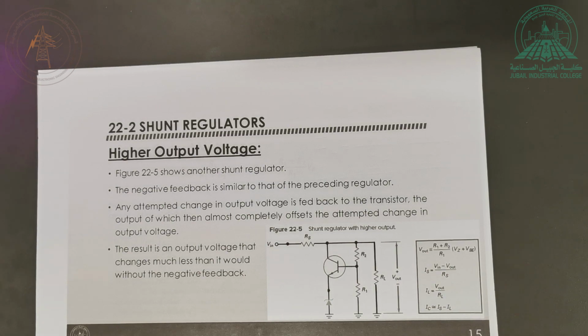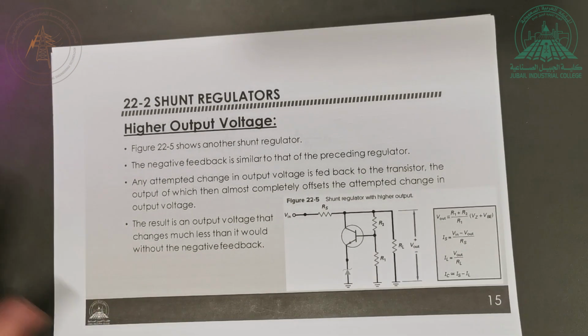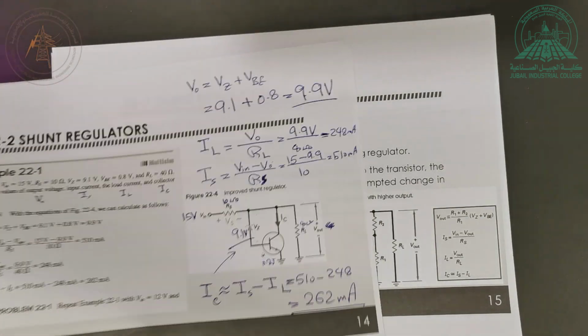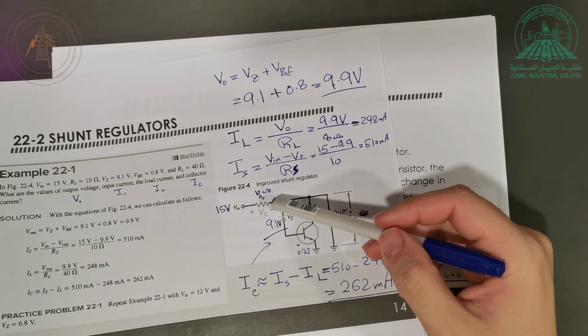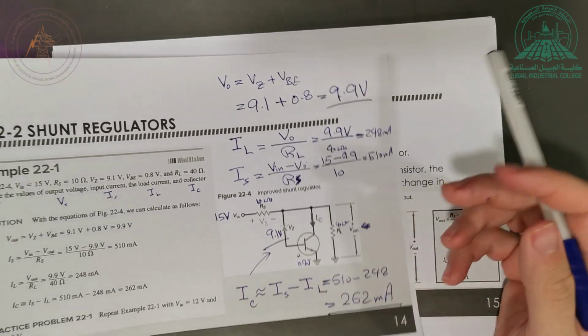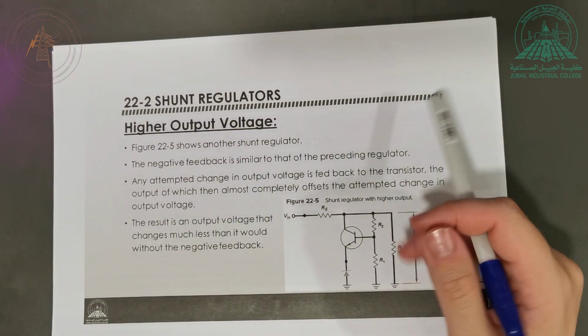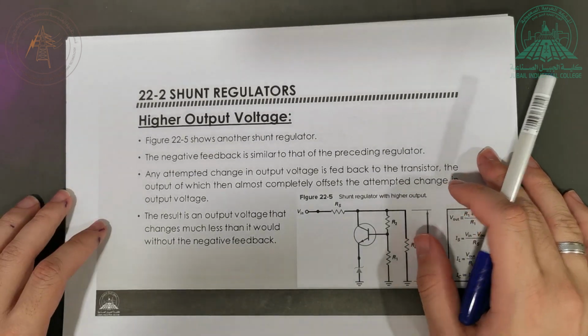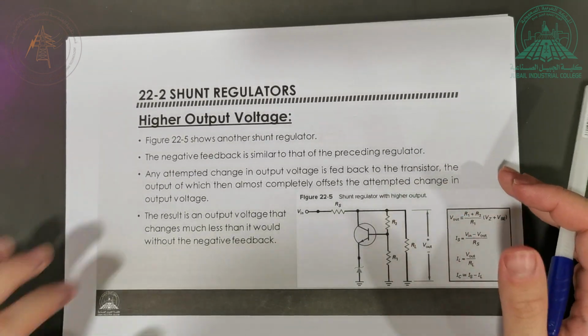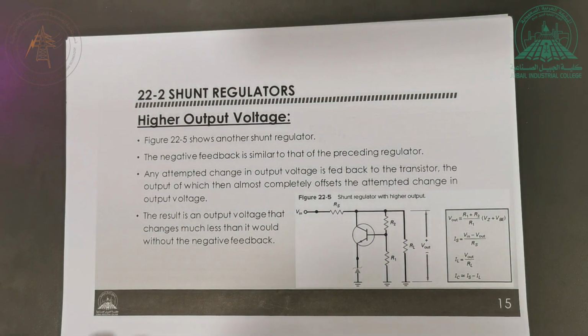Now we move to a new design. We have seen the issue of the low current. You can see now the Zener diode is not going to have high current moving in anymore. It's almost zero, because it's connected to the base of a bipolar junction transistor. Now in this design, we solve the other issue, which is the temperature